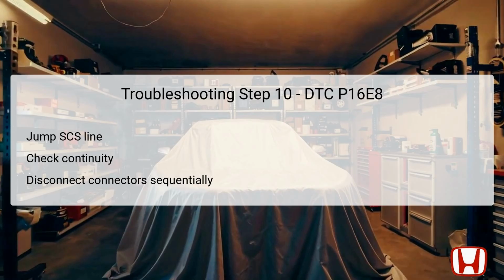Should the following steps confirm that the LIN wiring is intact, it's necessary to assess which component caused any interruptions. This testing procedure could lead to the replacement of components that may have interrupted connectivity without affecting the overall LIN communication network.